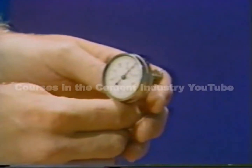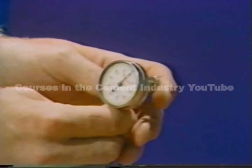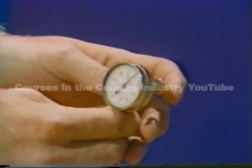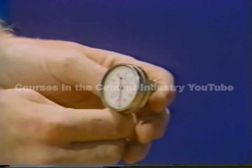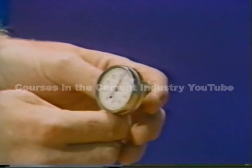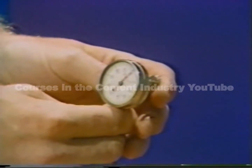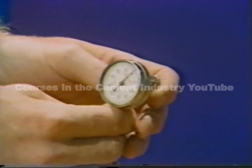Now let's move on to discuss the dial indicator as an alignment instrument. As you know, the dial indicator uses a plunger to move the needle on the dial. Inward motion of the plunger causes a clockwise needle movement for an increased reading on the dial. Outward motion of the plunger causes counterclockwise needle movement for decreased reading on the dial.